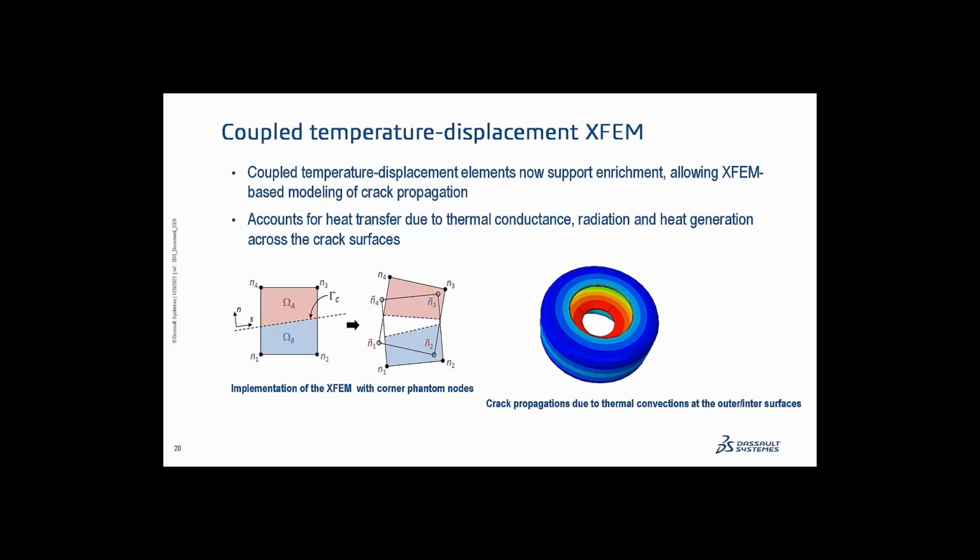Okay, switching gears now to enhancements that are primarily focused on Abaqus Standard. The first is the introduction of coupled temperature-displacement XFEM. If you recall, XFEM is a method for modeling crack propagation through a mesh, where the crack boundary doesn't necessarily correspond to an element boundary. That's kind of shown in the cartoon here.